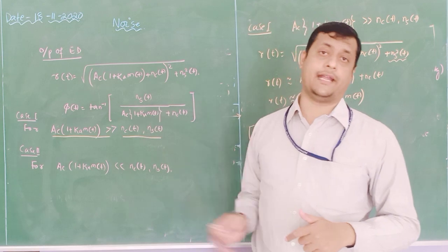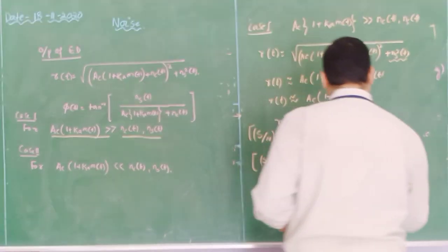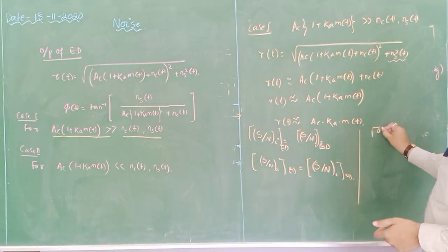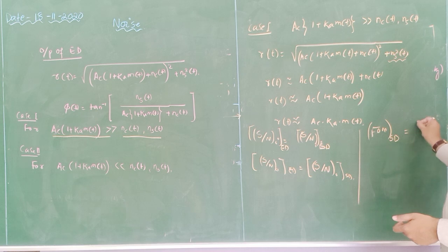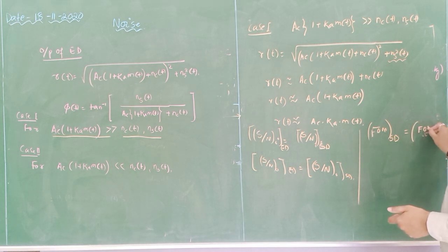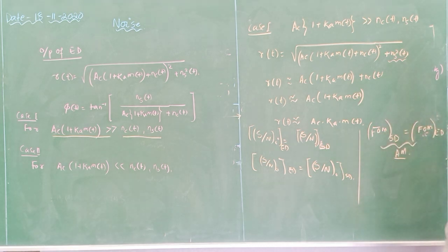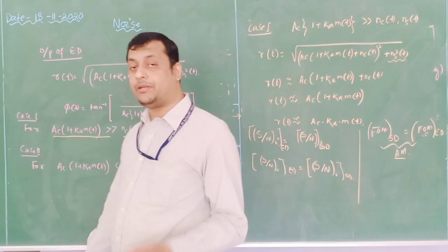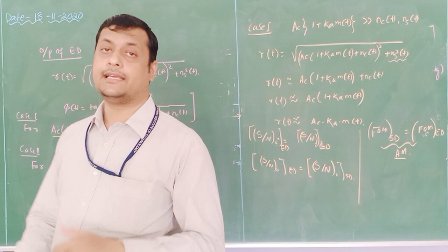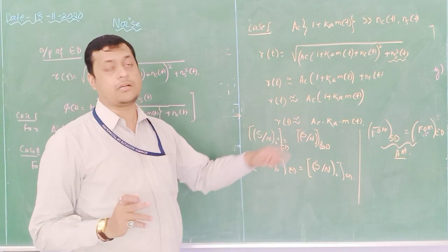using this envelope detection, your figure of merit is the same. The FOM for synchronous detection is equal to the figure of merit of envelope detection for the AM system. Only for the case when? Only for the case when the amplitude of the modulated signal is greater than the presence of noise. Then these are my conclusions.